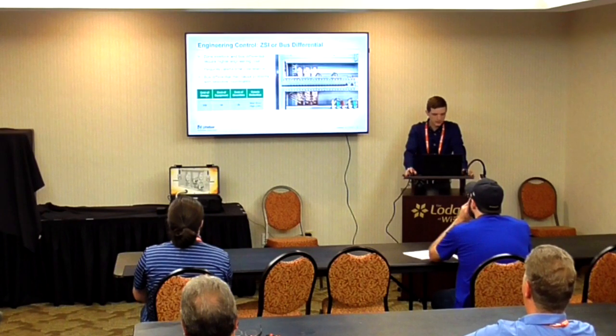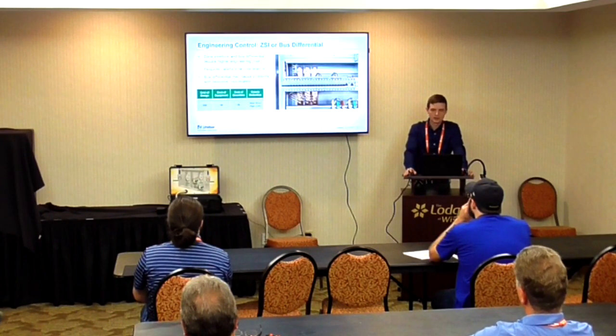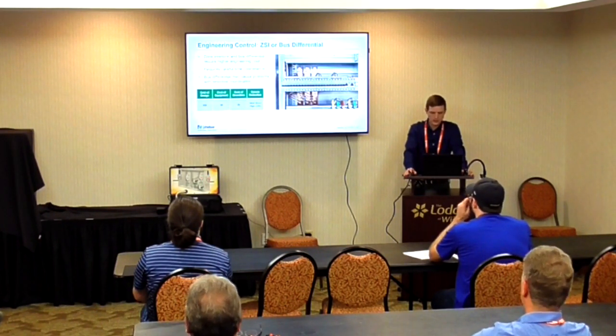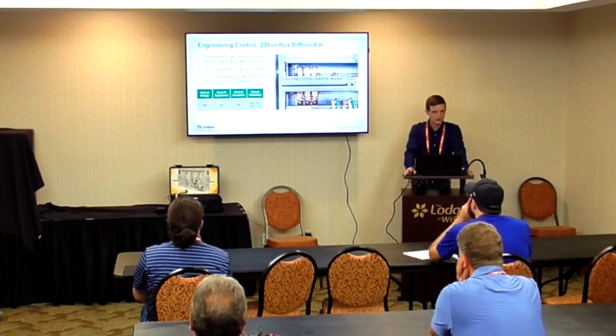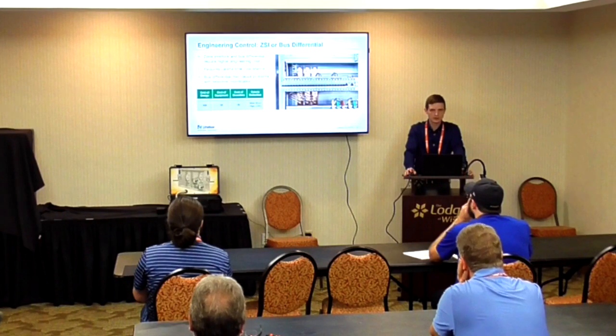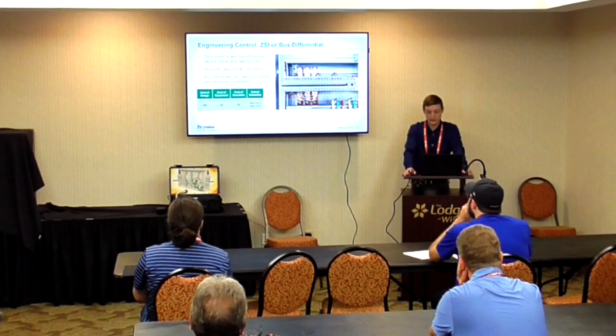These are very effective methods, but they do require a lot of engineering resources on the front end, because you're going to need to make sure that you have your breakers both selected properly and the settings configured properly. In a retrofit application, ZSI and bus differential both require a lot of CTs and new breakers, either at some or all levels of your equipment, and that's going to mean modifying the breaker all the way back to the MCC or panel board level.